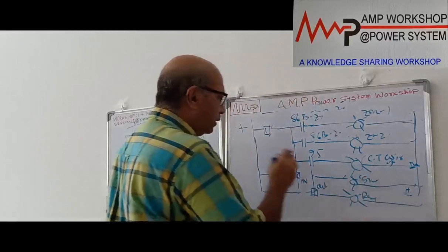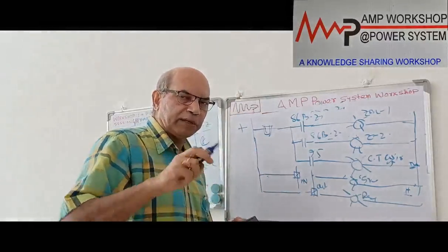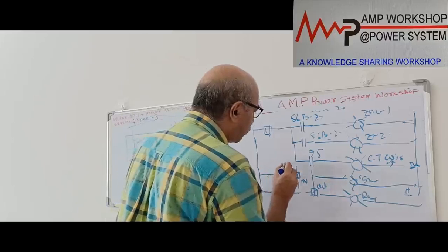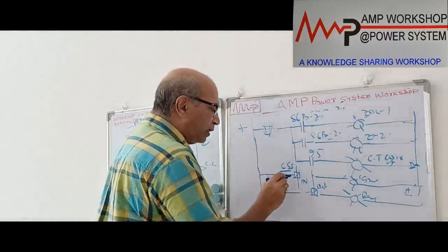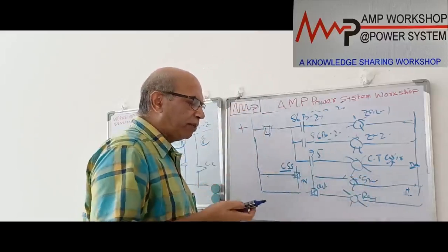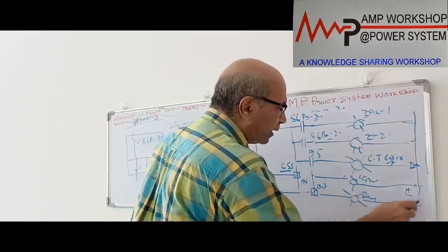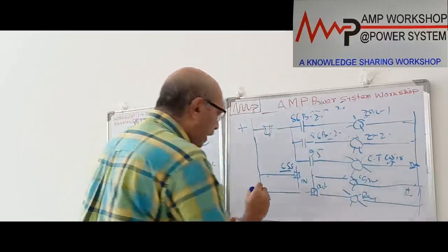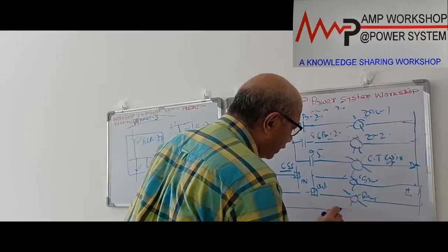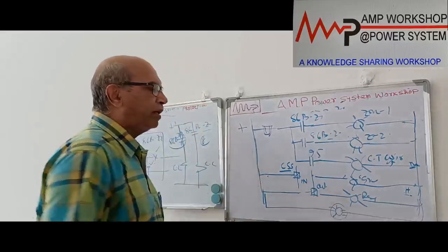So in the busbar zone protection system, the zone selection is a control selector switch. If the zone selector switch is in, then it will be green color. That means it is a secured condition. But if somebody by mistake puts the switch in the out position, then the busbar protection will be out of circuit, and immediately it will give a red color. That indication we can also get from here. Then at the end, we can check whether the entire bus wire is connected or not, that the bus wire is not loosened. In that case, we can put an indication lamp over here, so it will monitor the continuity of the bus wire.